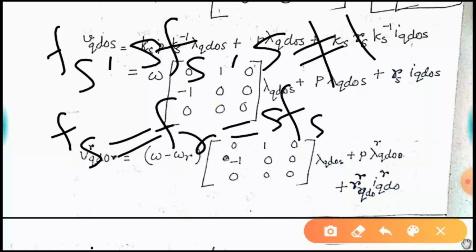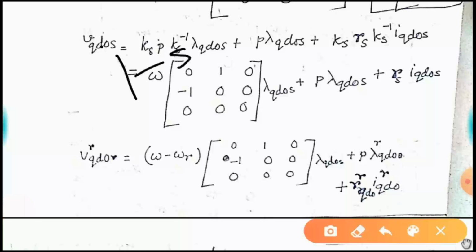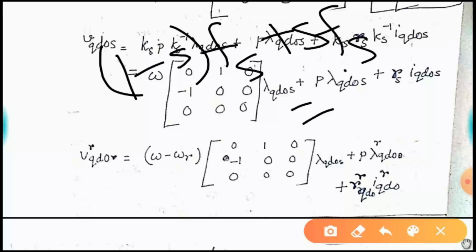Now when we consider that rotor's mechanical speed, this Fs is the frequency of the rotating magnetic field produced by your stationary stator winding, and this Fr is the frequency of your rotor winding conductor. But what is the physical speed of your rotor winding? If you convert it into frequency, you will see that the rotor physical speed is (1 minus s) Fs. So when you add (1 minus s) Fs plus s Fs, you get Fs.